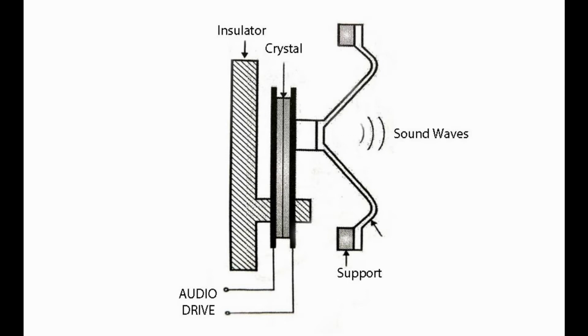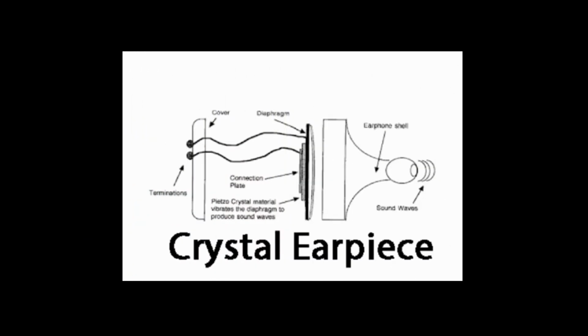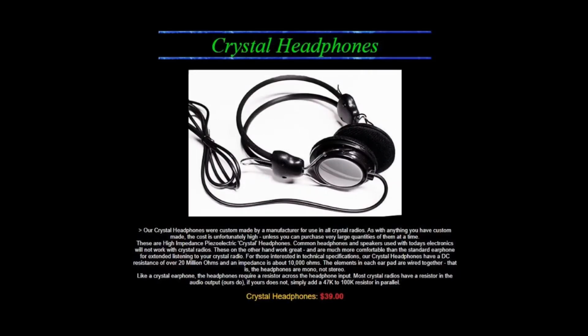During the 1950s, a ferroelectric ceramic material, barium titanate, began to replace the Rochelle salt in transducers. Unlike Rochelle salts, barium titanate did not lose its piezoelectric characteristics when exposed to high heat or humidity. The low cost and high impedance of crystal earpieces allows this technology to survive, even if fidelity is somewhat limited.